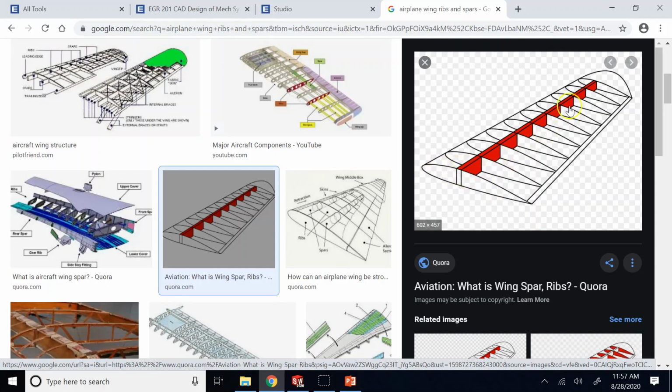And when you extrude it, even if you have this sketch, it's not going to be a simple extrude. It has a draft angle. And the draft angle is not even that simple. Why do you have a draft angle? Because the root airfoil is bigger than the tip airfoil. Okay, so it has a weird kind of draft angle too.